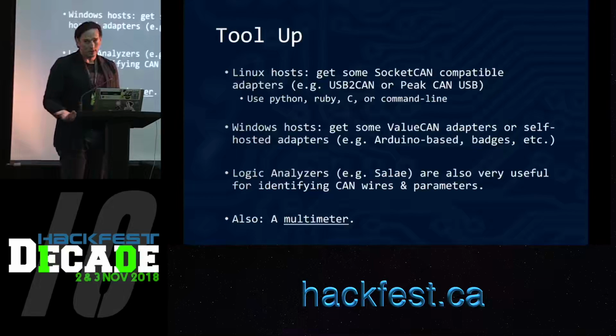Also, get yourself a logic analyzer, right? Saleae logic analyzers are not really that expensive, and they will decode CAN. And sometimes you're going to plug your CAN bus adapter in, and all you're going to get is just error codes back, and you have no idea what's going on. And there just isn't enough debugging tools out there other than a logic analyzer to save you. So if you really want to be able to figure out why you can't capture CAN traffic, you're going to need to go to a logic analyzer, so get yourself one of those.